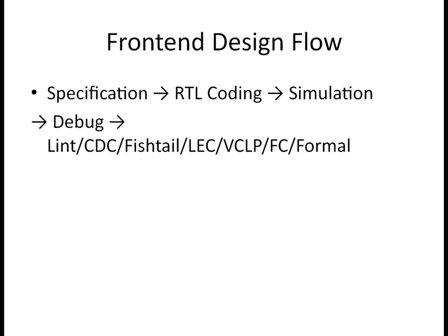In the constraint promotion flow, whatever constraints the IP is delivering, we are rolling up to the partition level. If you're running constraint promotion at the partition level, we'll take the constraints, the partition level RTL and partition level clock information, use this tool, and set all the input collateral as per the config, and we need to make sure your constraint promotion is done correctly.